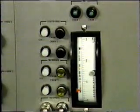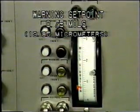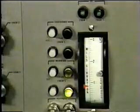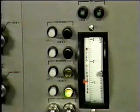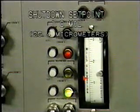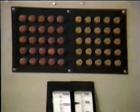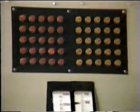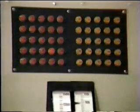If the monitor senses 0.75 mils of vibration, it will initiate a warning signal. If the vibration increases to 1 mil, the monitor will indicate a malfunction shutdown, causing malfunction light number 19 to illuminate and the K210 starting relays to drop out.